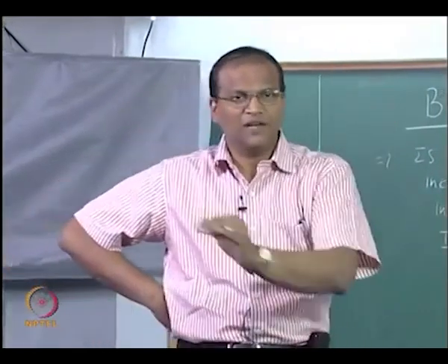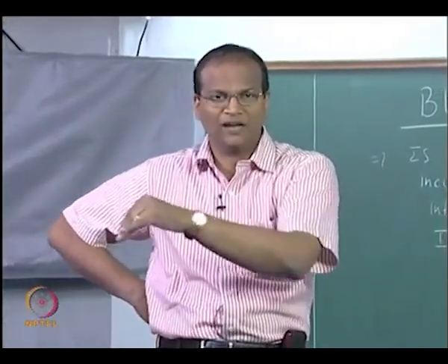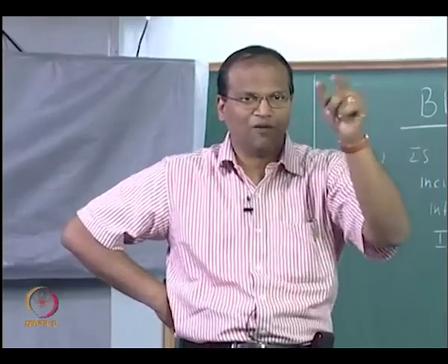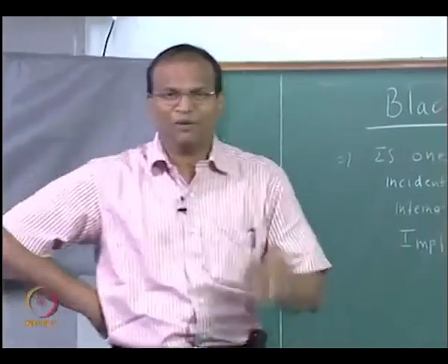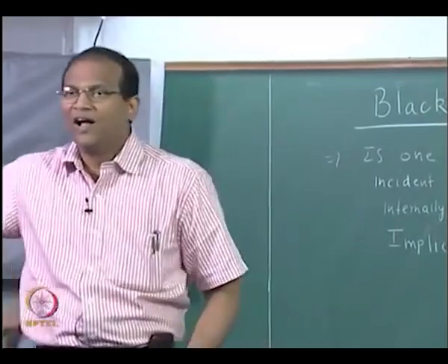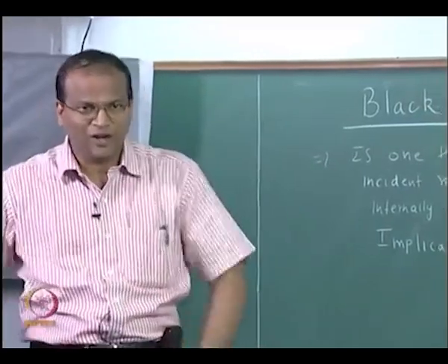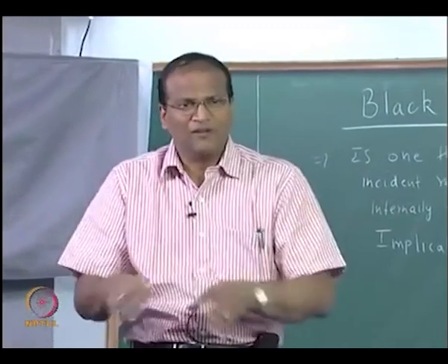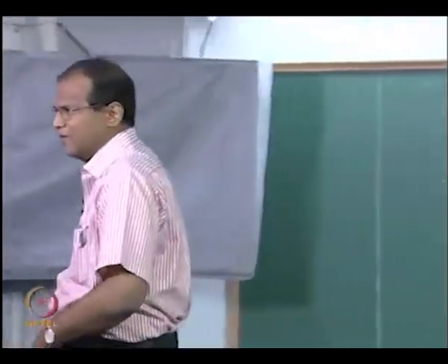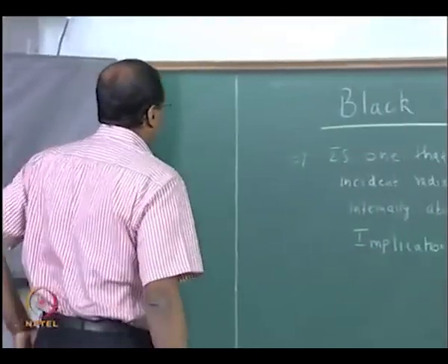Now you measure the emissivity, it will give 0.8, 0.88, 0.9 and so on, because there will be some places where you have not fully coated. After it dries, a second coat, maybe it will go to 0.92. After that it will asymptotically saturate. You cannot get that 1.00, but you will get something like 0.9495. For all practical purposes it is a black body. If you want to do experiments, you can say it is a high emissivity body. Okay.